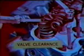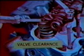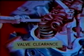The valve lifter originally was a solid piece of steel designed to follow the cam and transmit its movement to the valve. This solid type of lifter still is used on some engines. With solid lifters, it is necessary to set a small amount of clearance in the valve train. This clearance assures that the valve has room to close fully, but may also allow some noise to develop as wear occurs. Adjustments of valve clearance are part of periodic maintenance.